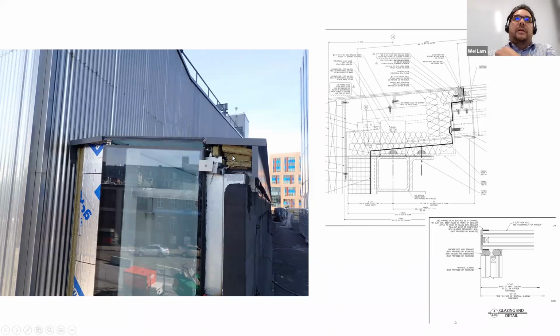And then I think there were comments around the insulation, but then you think about these end conditions which were not anticipated. And I think this is why we took this particular photo, to understand how the roofing was coming in, and also how this end condition was being resolved. If you can see my arrow right here, you can see the end of this mullion. This is the raceway here, I think right about here. So this end condition needed to be capped off in order to provide some continuity to the various barrier control layers.